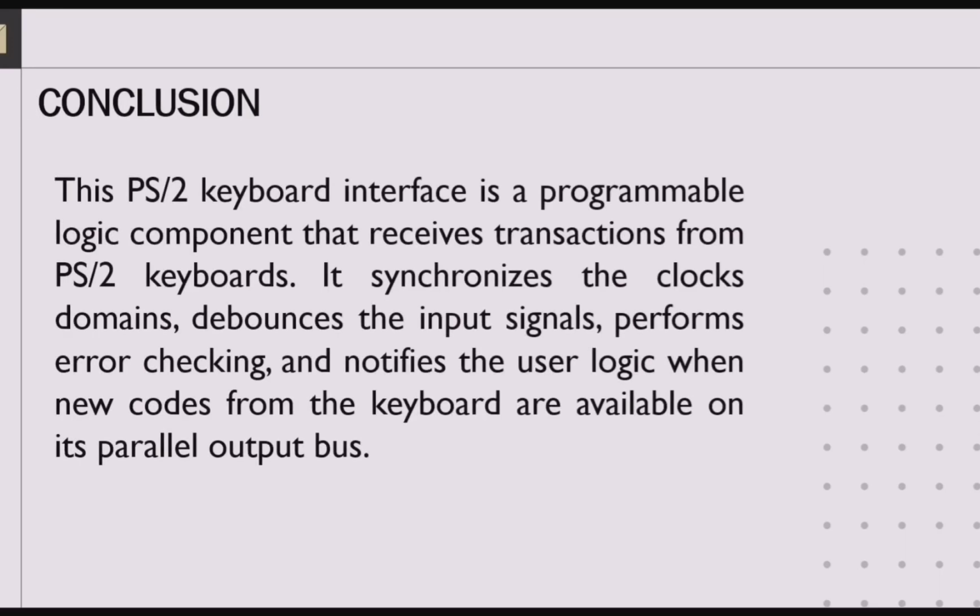In conclusion, this PS2 keyboard interface is a programmable logic component that receives transactions from PS2 keyboards. It synchronizes the clock domain, debounces the input signals, performs error checking, and notifies the user logic when new codes from the keyboard are available on its parallel output bus.